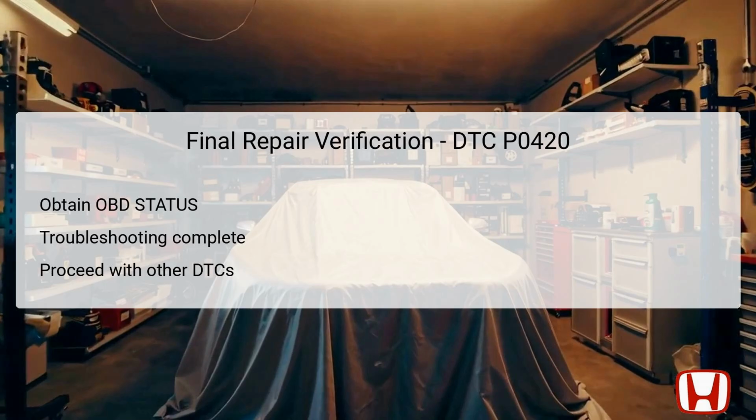The final step in verifying repairs for DTC P0420 involves scrutinizing the OBD status after performing the necessary maintenance or replacements. If the HDS indicates a passed result, it signifies that troubleshooting is complete and the catalytic system is functioning as designed. However, if any other pending or confirmed DTCs have appeared, the technician should address those issues prior to considering the overall repair as finalized.